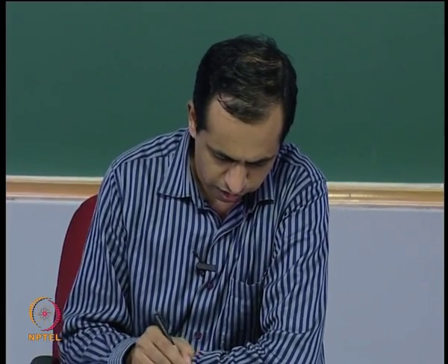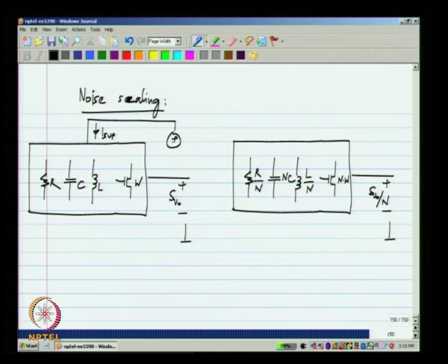From the power supply, or in general the currents anywhere, I will consider the power supply because that is what determines the power dissipation. So, let us say this is VDD and that draws a current I_sub, let us say. What is the current drawn from this? It is easy to see that every branch current in the new circuit will be n times the branch currents in the original circuit. So, the current here will be n times I_sub.